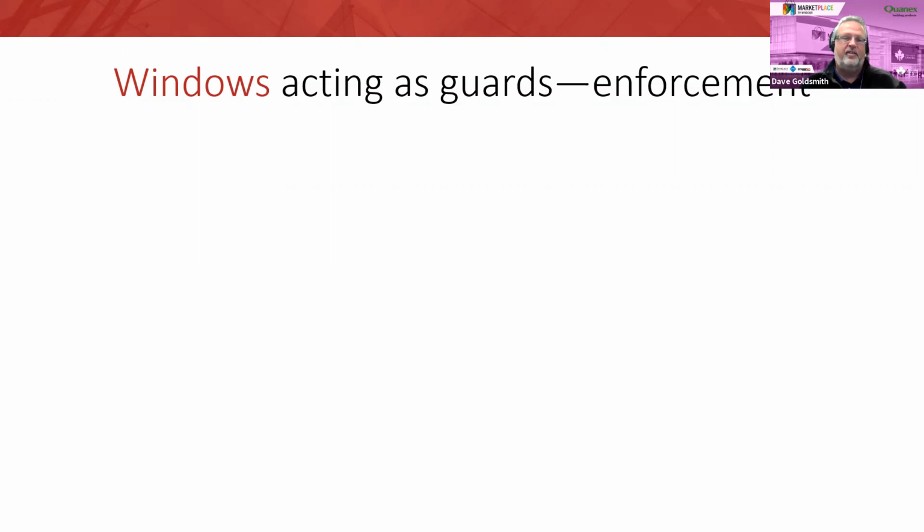It's just that the guard height is lower in dwelling units than it is in public areas. So I don't think the occupancy makes a difference for guard load, right? It could be in a public area. Right. The guard height is higher in a public area than it is within a dwelling unit, is the language that they use in the code.